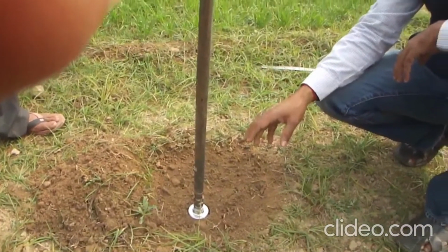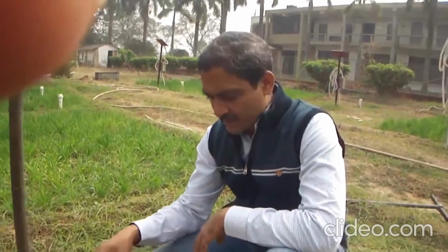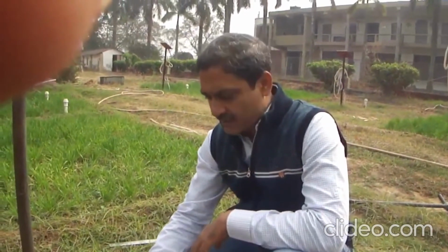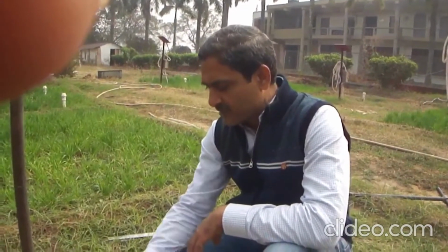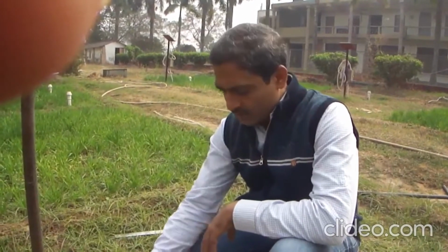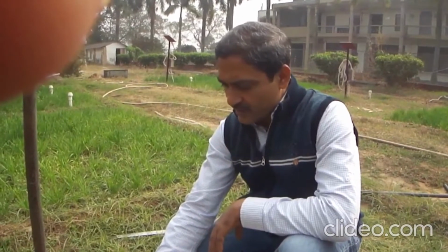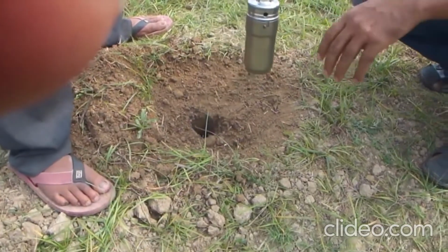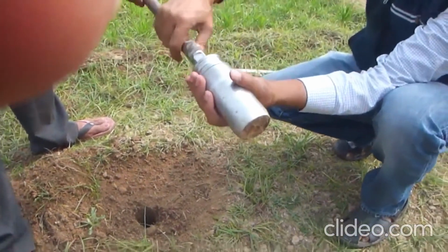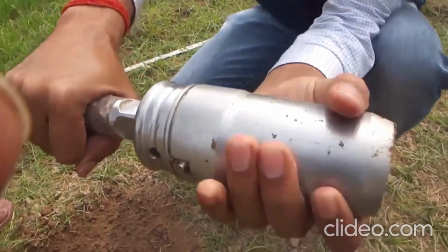However, when we are interested in taking a sample from the deeper layer, say 20 centimeter or beyond, first we remove the surface by using the auger. Our topsoil layers are removed by using the auger and then we drive this core inside. So let us take this first sample of the near surface, see how it looks, and keep it outside. Now open this with care, just like here.